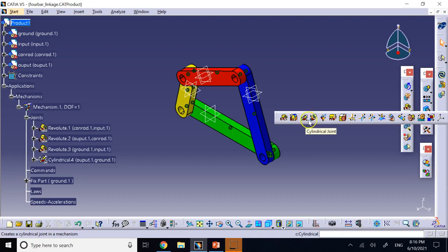Although the screw goes inside the other part, the nut, backward, forward, and it spins also, that spinning and that advance motion backward or forward, those 2 motions are not independent. One depends on the other one, and degrees of freedom have to be independent from each other. So actually, screw has 1 degree of freedom, cylindrical has 2.